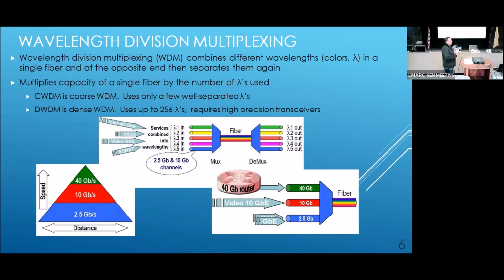And that is how FiOS works. For any of us that have FiOS with fiber to the house, it uses coarse wavelength division muxing, and it puts telephone, the old analog television, which actually becomes digitized, on its own wavelength on the FiOS fiber. Then your internet has its own wavelength on the FiOS fiber. And then the television band comes in with a whole different wavelength on the fiber. So the FiOS is actually multiplexing several wavelengths at once.